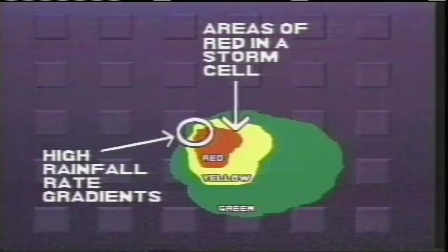Weather cells, which are very active, in particular thunderstorms, contain high levels of turbulence along with excessive amounts of precipitation in the form of rain and/or hail. Flight crews can use the following visual clues to help identify these storm types and assess their hazard potential to better plan their evasive maneuvers. A rainfall rate anywhere within a cell displayed as magenta or red.